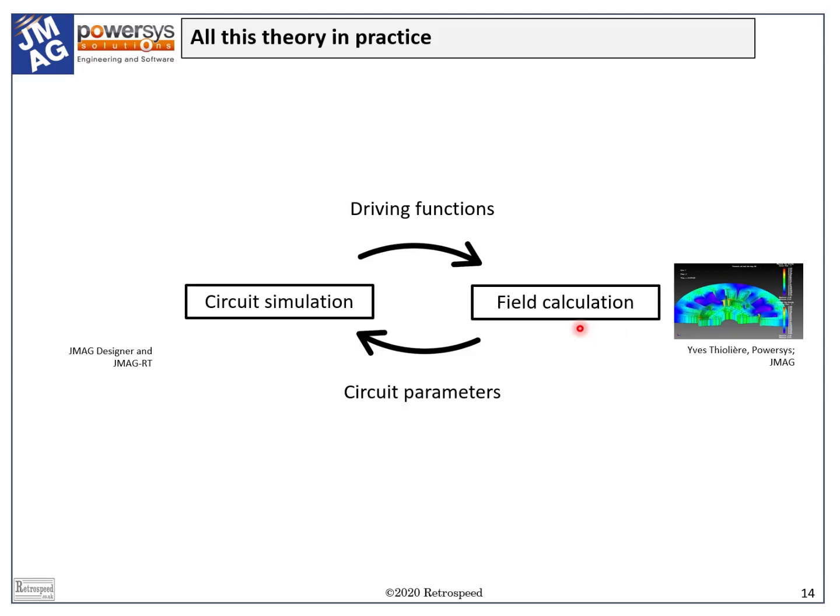What happens to all the other harmonics? Well, they produce parasitic effects, torque ripple, additional losses, and they appear as additional leakage inductance, harmonic leakage inductance, but all these effects are usually of secondary importance and do not change the fundamental control behavior of the machine. Oh yes, and I haven't even mentioned eddy currents or core losses.